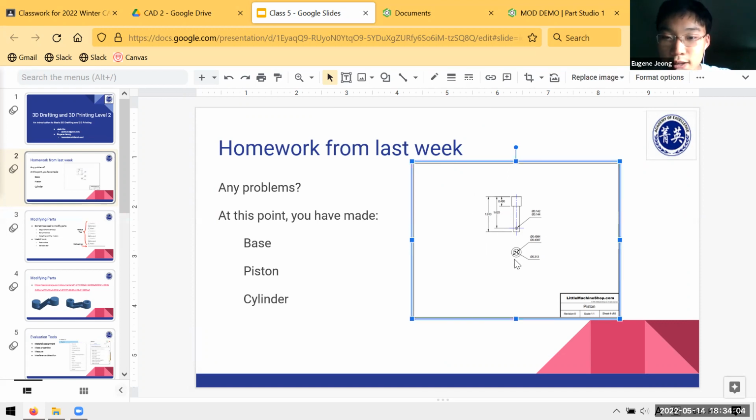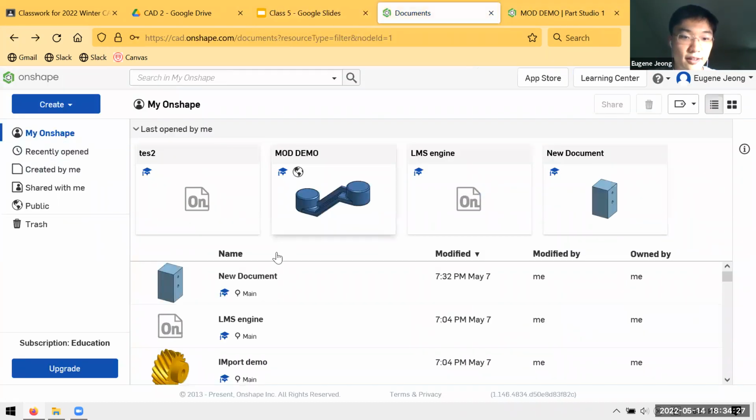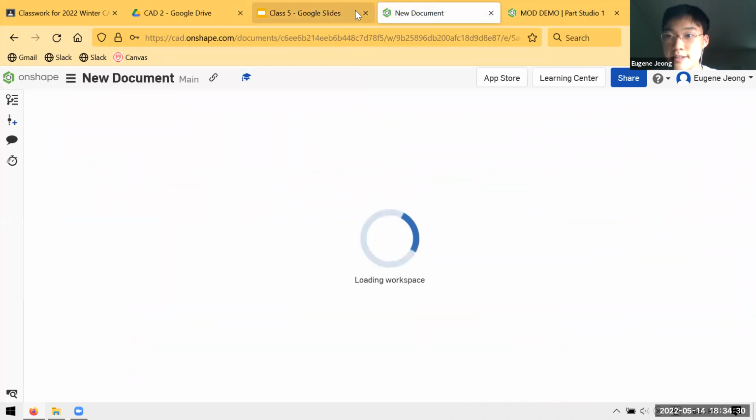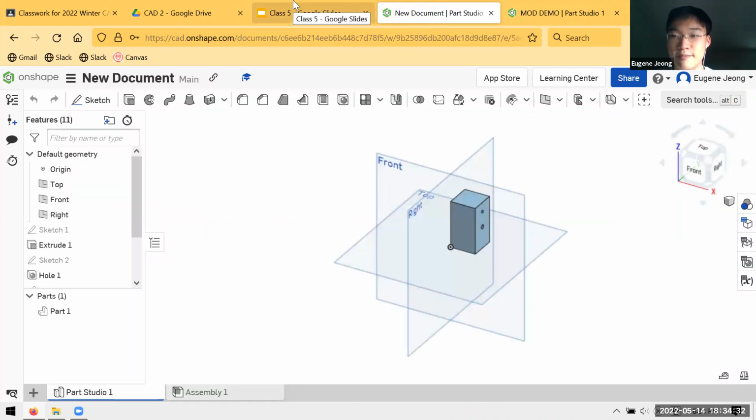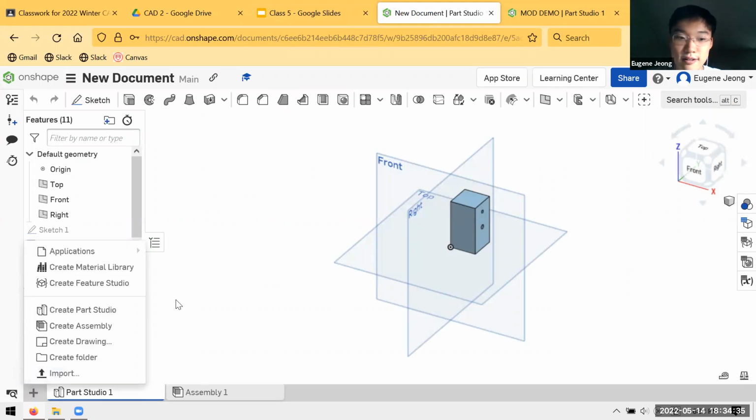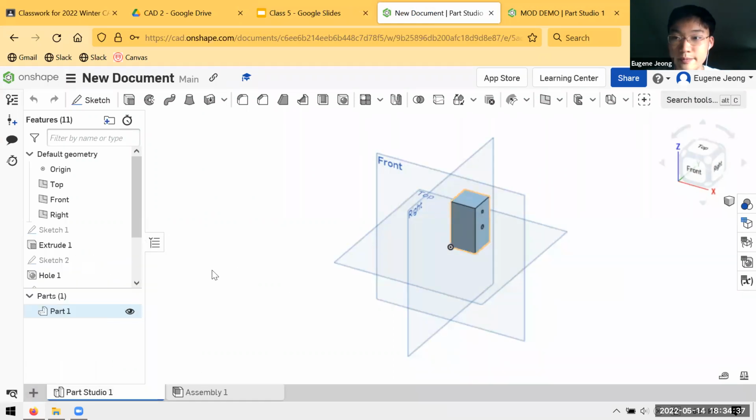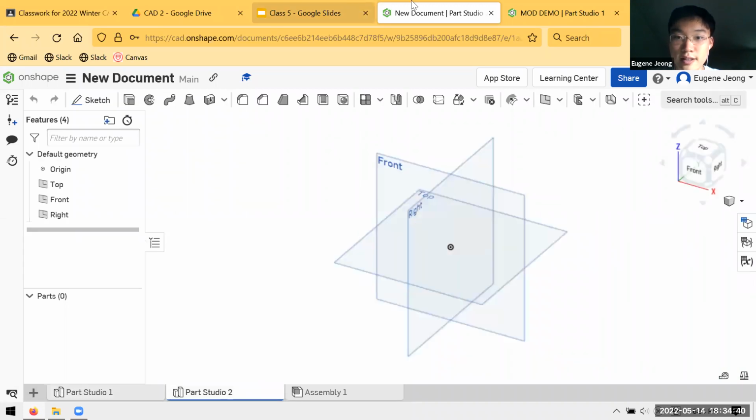But hopefully from this drawing, you got the idea that this is supposed to be two cylinders basically stacked on top of each other. One kind of long rod-shaped cylinder and one stubbier, thicker cylinder. So if you got that idea, then the execution is hopefully not too bad. But the idea is you can just extrude two cylinders, one right above the other.